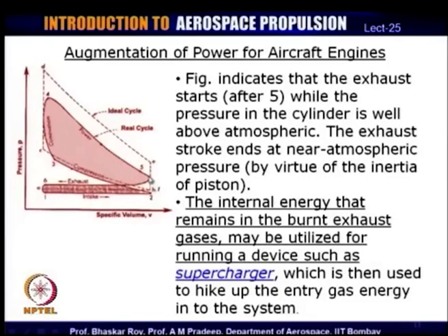So, the difference between the exhaust pressure and the intake pressure starts going up, and as a result, this loop which we see here, the intake exhaust loop, starts consuming more and more. This area becomes higher and higher, which is the non-productive or non-power creating loop of this cycle, and as a result a lot of the power that is produced actually goes into this loop, and it is not available at the end as BHP. Now, this is a problem, and as a result the available BHP would go down.